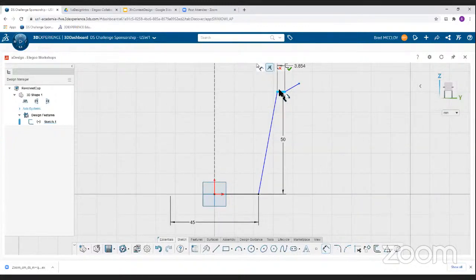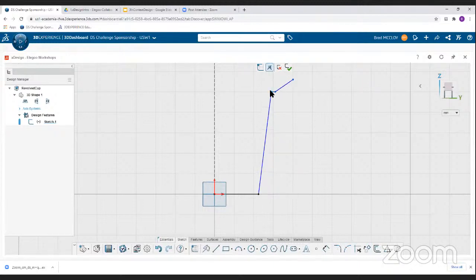The little lip on the cup, let's make it really small, maybe 2 millimeters wide. And from here to here, this top lip, maybe about 6 millimeters. I think it should be a bit taller. Okay, so now the cup's starting to be a little more defined. My cursor has got the dimensioning bar on it. So you can see it knew I wanted to keep repeating those dimensions, so it kept it highlighted. So when done, I hit escape, dimensioning bar goes off. And as expected, there's a lot of things we're not defined yet, so we can still move stuff around.